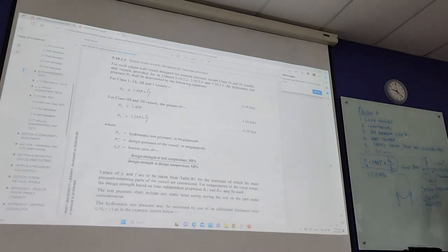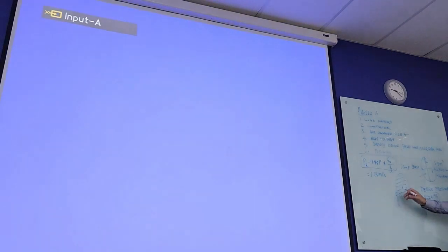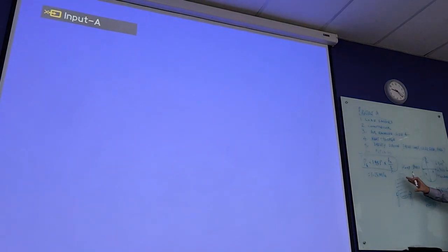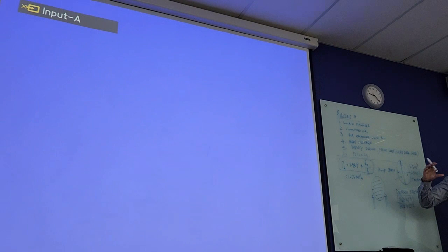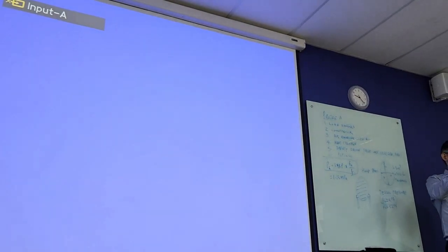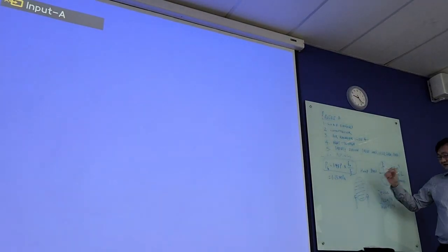The volume of the steel, you need to know the mass, followed by the water, all the water volume inside the receiver. Then you calculate the total mass of it, to see whether our column can support the weight. Alright, so this is what we do: the mass of this air receiver plus the water required inside the tank for the hydrostatic test.